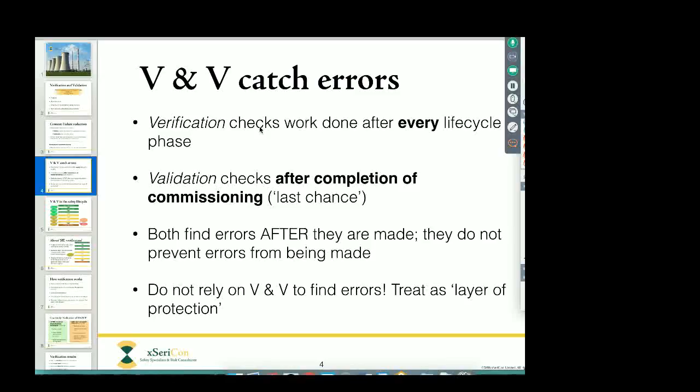One thing I'd like to mention is quite often if we have a robust system, especially for verification, it's easy to allow ourselves to become over-dependent on it. For example, let's say I've done a HAZOP study and I'm writing the HAZOP report. So maybe I'm feeling tired, maybe I'm feeling lazy. I just write the HAZOP report and it seems good enough to me, and I'm not too worried about it being absolutely right because I know somebody else is going to check afterwards. Now that is a disaster, because what I've essentially done there is I've lost a layer of protection.